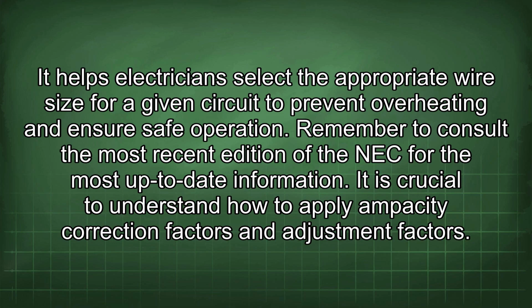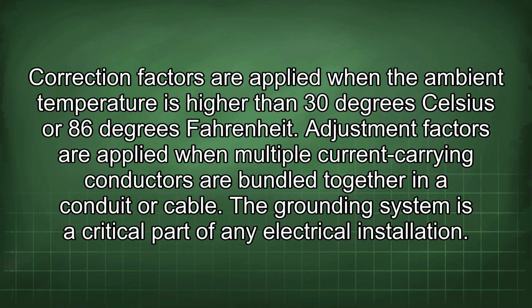It is crucial to understand how to apply ampacity correction factors and adjustment factors. Correction factors are applied when the ambient temperature is higher than 30 degrees Celsius or 86 degrees Fahrenheit. Adjustment factors are applied when multiple current-carrying conductors are bundled together in a conduit or cable.